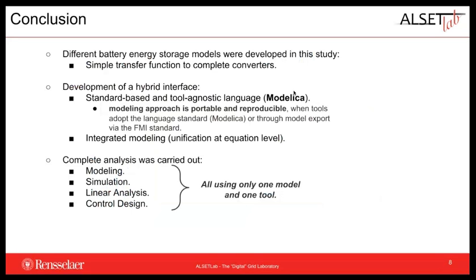Therefore, in this work, we were able to create a battery model in Modelica that can have different levels of detail. In addition, the hybrid interface was also assembled using Modelica, and it unified different systems at the equation level. This allowed us to perform modeling, simulation, linear analysis, and control design using the same model and the same tool.